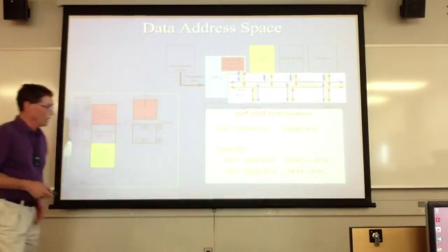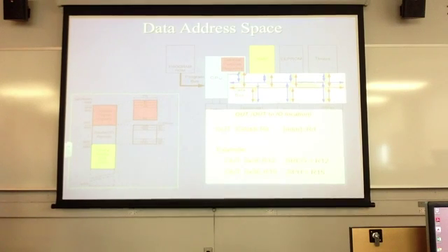All right. So for example, if I do an OUT to 3F, R12, 3F happens to be the location of my status register. So I'm going to put the contents of R12 into the status register. Or I can have the contents of R15 going into 3E. 3E happens to be the location of the stack pointer high. All right, so I can write to there. I can do an OUT of R12 to the stack pointer high. I can also go IN: I could take the contents of the status register and bring it in.